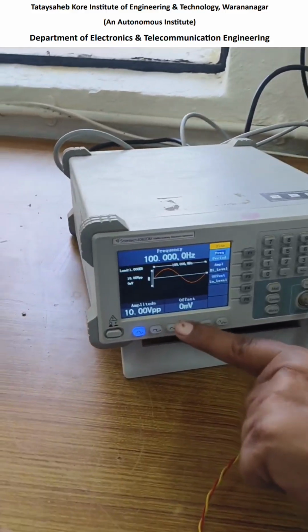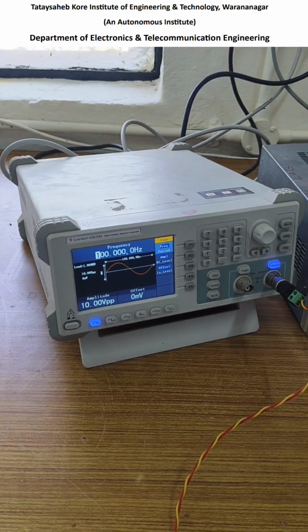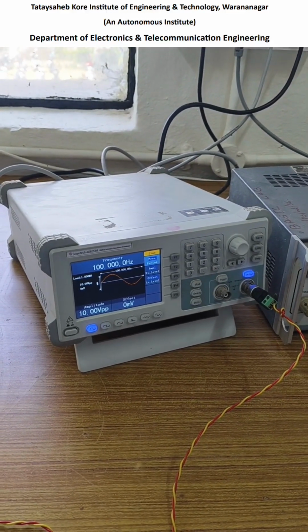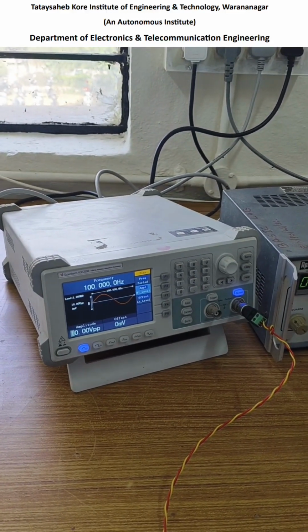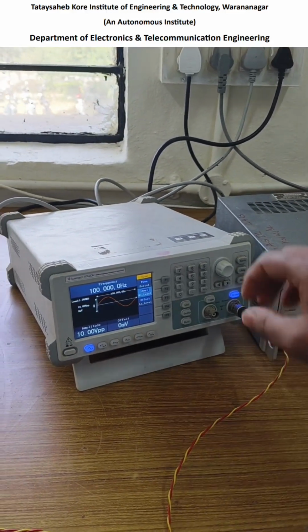What is the amplitude here? 10 millivolt. That you have to change to which value? 20 millivolt. So now, where is the blinker? On frequency. First change that blinker to amplitude. So press F2. After pressing F2, the blinker will change to amplitude. Now press 20.